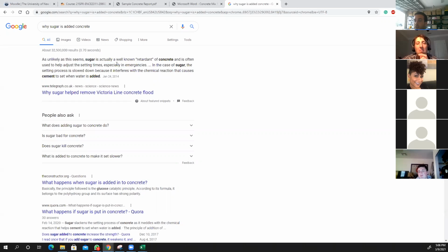So let's say you are going beyond 90 minutes, you can add sugar, and there are different admixtures, you can increase the timing, but it has to be on the receipt as well. If there is something extra in the concrete that you don't know about, then that's the problem. And if it's over 90 minutes and they don't have the admixtures, they don't tell you what's going on, and they just want to add more water or extra stuff in the concrete, that's going to be beyond the specs given by the engineer.